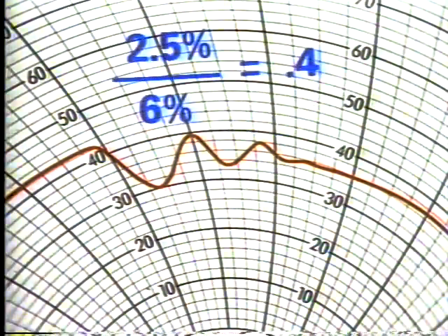So the decay ratio was about 0.4, which was too high. The technician knew that something around 0.25 or 1/4 is what it should have been. So the curve indicated cycling, excessive response time, and a small offset. All of these things pointed to the gain being too high.